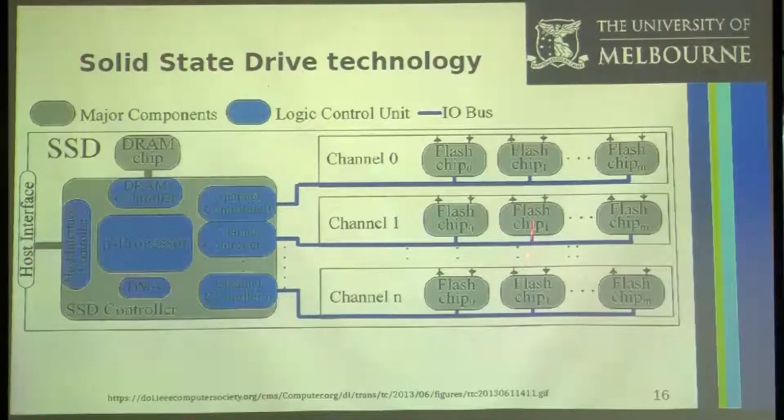And I just have this diagram that I found that seems to be okay. The main thing with a solid state drive is that it's essentially like a little computer. It has banks of memory. These are channels, these are the banks, so there are M banks and N channels in this solid state drive. These are really just like RAM in some sense, with controllers to read and write to these NAND gates. And then a DRAM controller as a buffer, essentially a DRAM chip, and then a host controller.